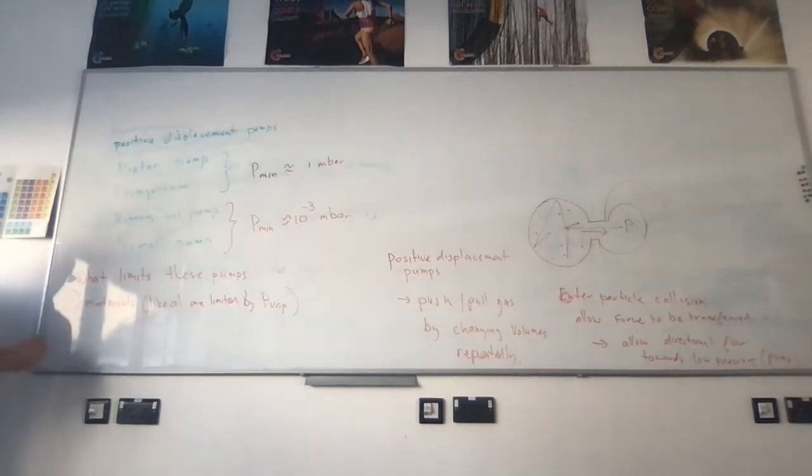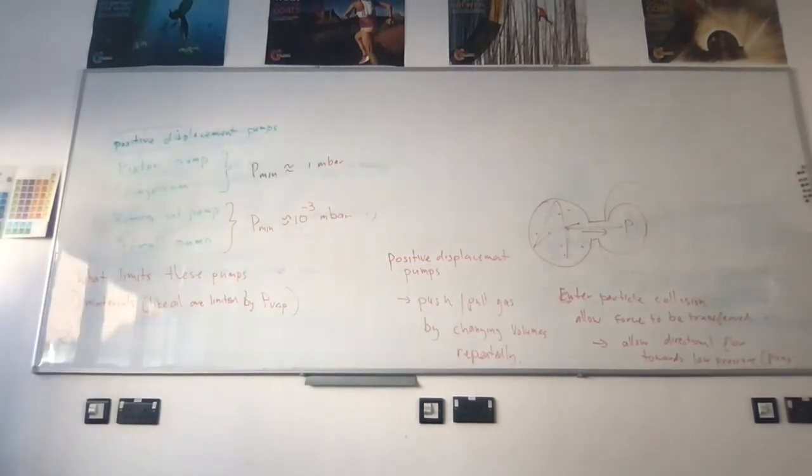But there's also a more fundamental reason why these pumps would stop working. They pump down to 10 to the -3, and that's it. They can't do anything better than that. You could use an oil which has a vapor pressure of 10 to the -6. We have these oils, bloody expensive, pretty toxic, but they exist, and still the pump is not going to reach 10 to the -6. So if you had an idea of why they can't continue working,